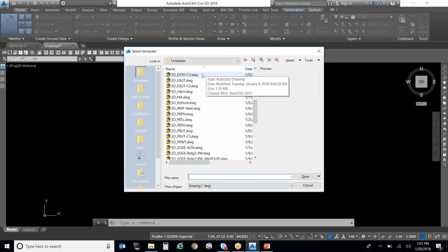You can see where the conflict is. A lot of times it seems like we have a design and something changes and we need an extra area. So we maybe have really good survey data, and then someone says, oh, I need some topo in this area, which I would give them like USGS 30 meter DEM or 10 meter DEM, whatever is best available. And you create a surface, like, you can't finish the design using that. Like, you have to then have survey go out and finish.